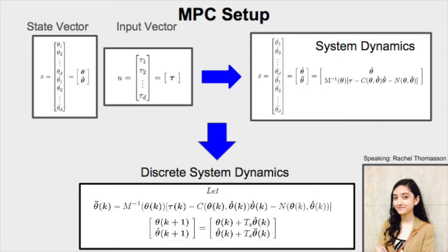Our controller was a model predictive controller that performed constrained finite time optimal control at multiple time steps using a modified version of the standard LQR controller we learned about in this class. In particular, it was modified for the purpose of trajectory following, with a similar setup to the one presented during the first midterm, with the cost function itself changing every time step. We chose this particular controller because we wanted to implement a form of optimal control while minimizing extraneous torques or movements. This is in line with the goals of cooperative robot control we outlined before.